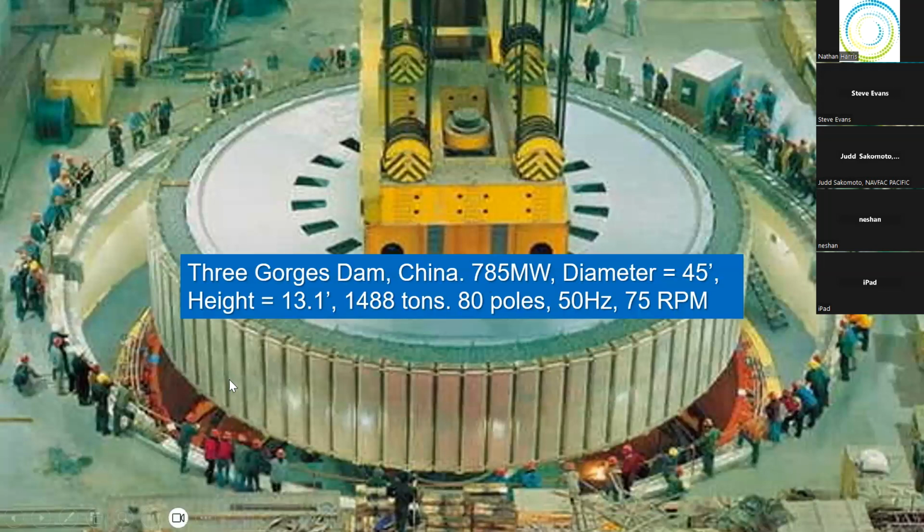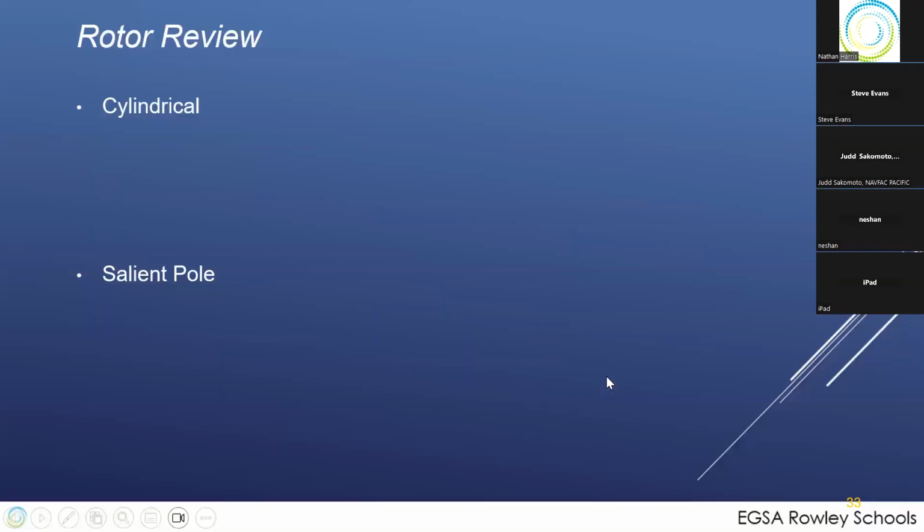He's ready. So anyway, this kind of inertia is what we have in our grid today. If you parallel even your 2 meg machine up against this guy, and it had some kind of fault in your machine, it wouldn't even see it. It'd just blow your breaker on your machine, and they wouldn't care. So generally, the utility doesn't care about your generator at all. They care about what happens to their grid. They don't want you backfeeding their grid and hurting their people, but they don't care about your generator. So you're insignificant to them.